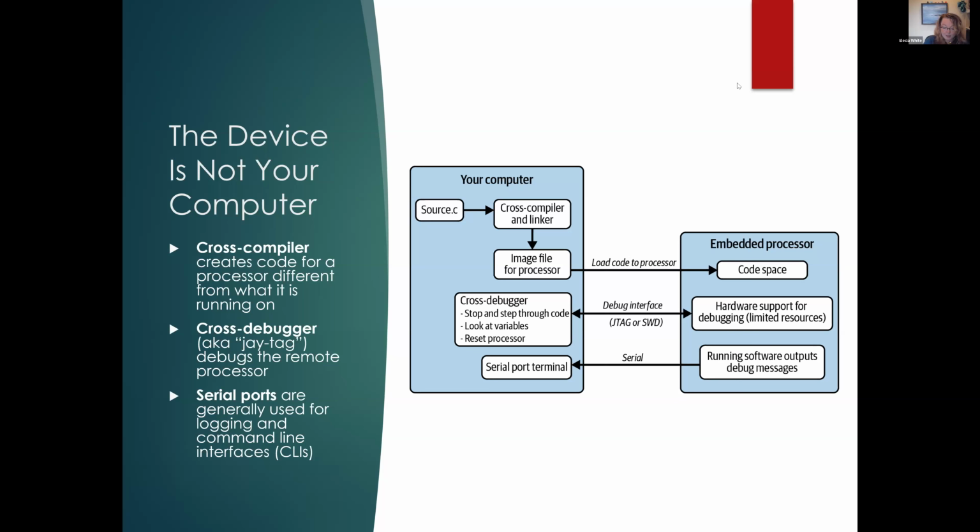For example, adding a breakpoint causes the processor to modify the memory-mapped, memory-loaded code, to say stop here. So you put in a breakpoint, and as it goes through, the code will be modified to say stop here. However, if your code is executing out of flash or any other sort of read-only memory, instead of modifying the code to say stop here, the processor has to set an internal register, a hardware breakpoint, and compare it at each execution cycle to the address being run. And when they match, it will stop. Are you there yet? Are you there yet? Oh, let's stop here.